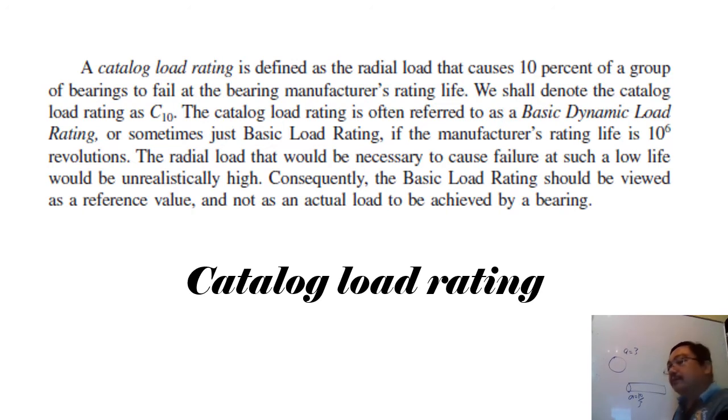Consequently, the basic load rating should be viewed as a reference value, not the actual load to be achieved by a bearing. So, what does it mean by catalog rating? I just want to explain what it means by C10 life. Basically, if you are familiar with the bell shape, in mathematics class you have learned about this bell curve, in statistics.